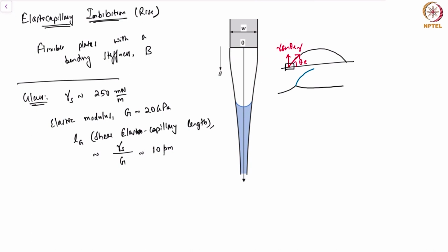In other words, the deformation just because of surface tension or surface energy is so small that you will practically never observe it. So for all practical purposes, as far as only surface energies are concerned, you can assume glass to be fairly rigid. Glass is not going to deform. This is also true for metals as well.